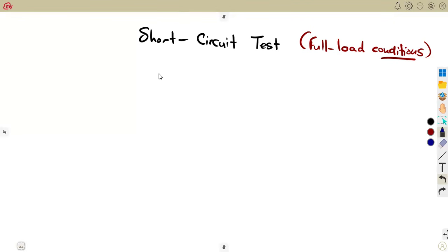So a short circuit test can be conducted on the primary side, and that is placing the instrument on the secondary side. So this is how we're going to have our circuit diagram. Let me just present the circuit diagram, how we're going to have this time. Remember, on the primary, we're going to have our voltage there. Then we're going to have our ammeter to measure our current in a series combination like that. Our wattmeter,